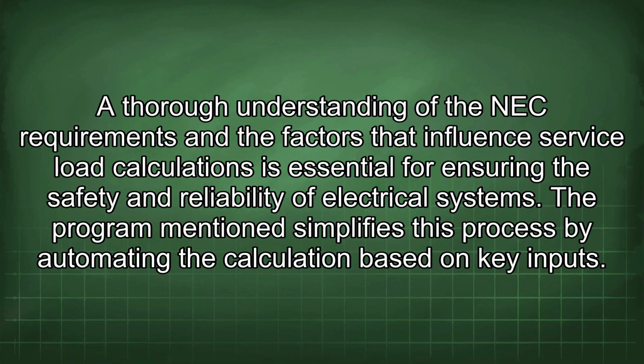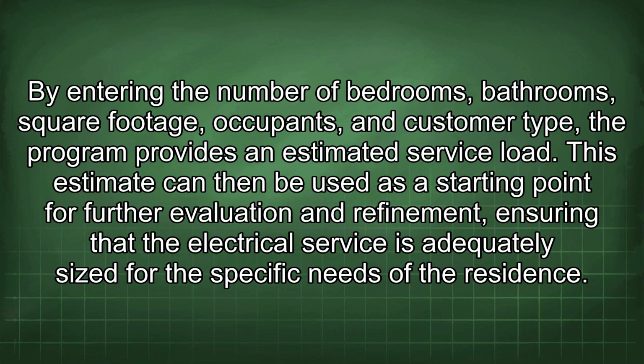The program mentioned simplifies this process by automating the calculation based on key inputs. By entering the number of bedrooms, bathrooms, square footage, occupants, and customer type, the program provides an estimated service load. This estimate can then be used as a starting point for further evaluation and refinement, ensuring that the electrical service is adequately sized for the specific needs of the residents.